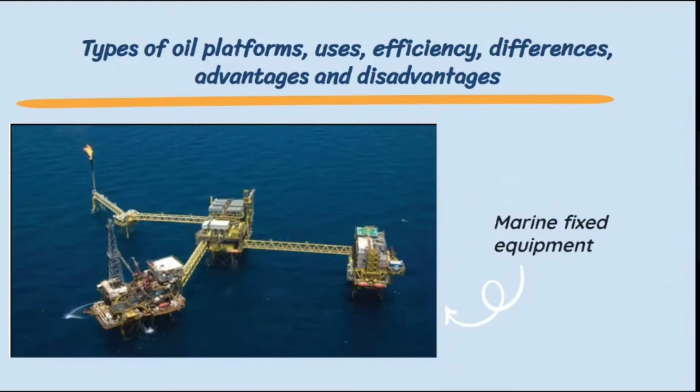In recent years, fixed platforms have represented the most common structural solution for production and drilling ensembles. However, drilling works in depths greater than 400 meters are not productive, since it is not profitable to build and install a fixed platform with such a heavy and long substructure to lean on the seabed. Fixed platform complexes are generally made up of different modules.